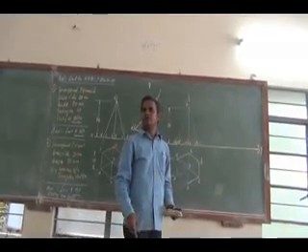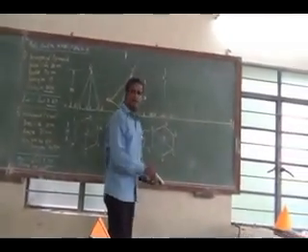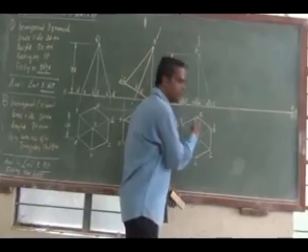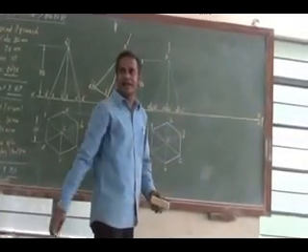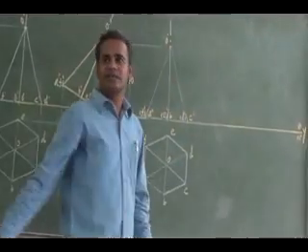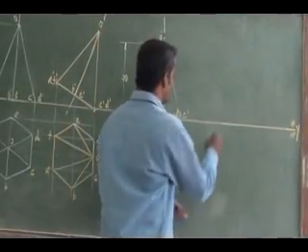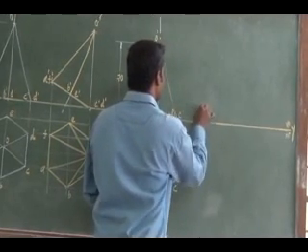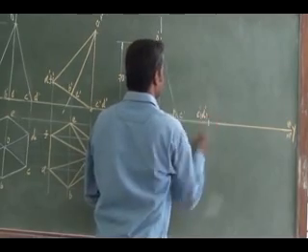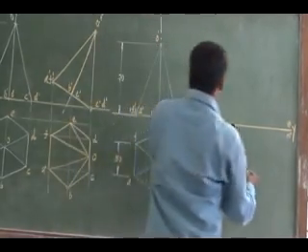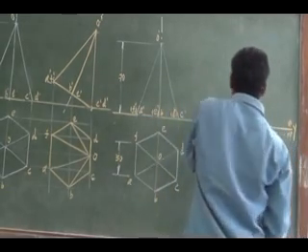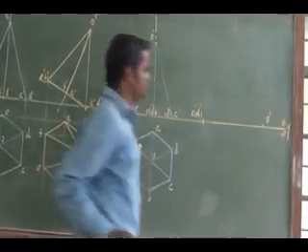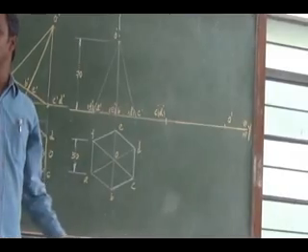It is lying with a triangular slant face, and the triangular slant face which I am going to keep on the ground is nothing but CDO again. So the CDO triangular slant face is seen in the front view as a line. So I can mark CD on the reference line. See here, this is my C dash, D dash. Then measure CDO, so you mark it conveniently on the reference line. This is my O dash. So CDO has to be marked on the reference line.